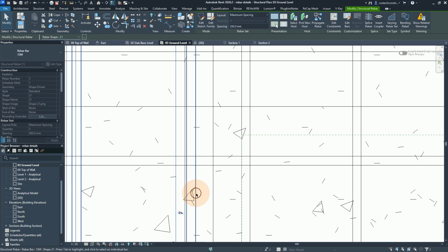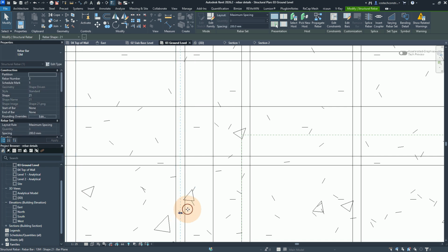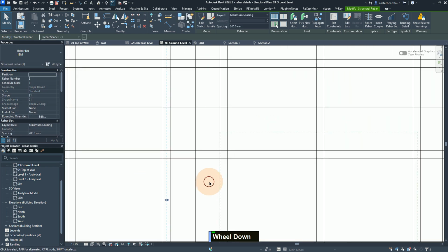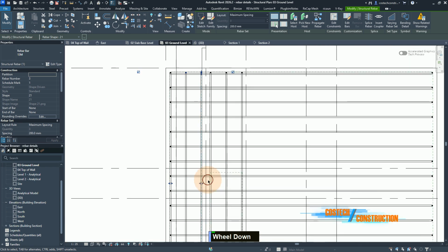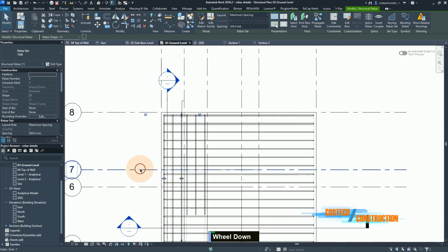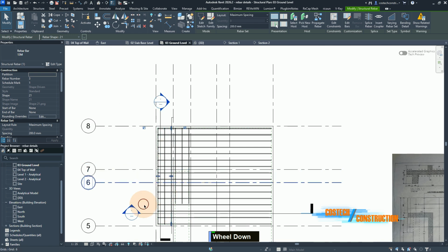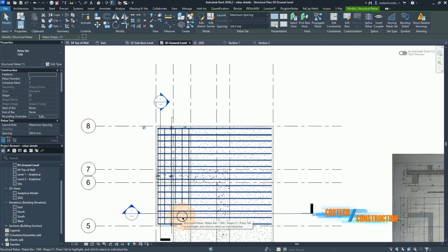Then I can select the other Rebar Set, then align it to the previously moved Rebar Set, which was this one. We'll align it to the midpoint like that. And so now we have our third Rebar Set in place. Remember that we can clear the clashes at the 3D by selecting the Rebar Set, then go to Edit Bars.